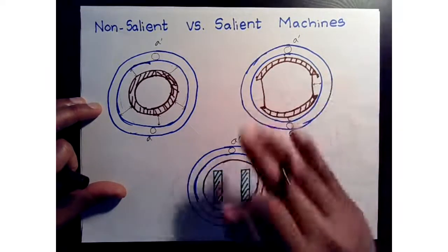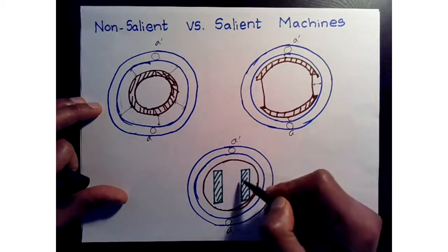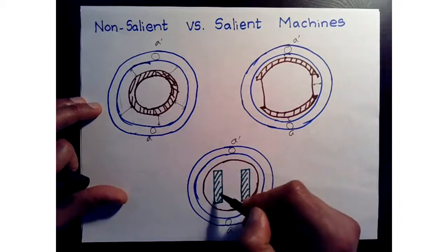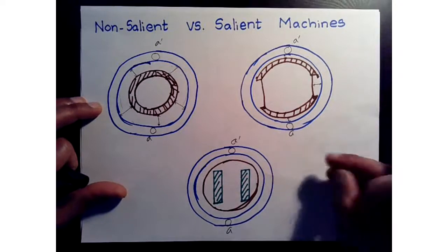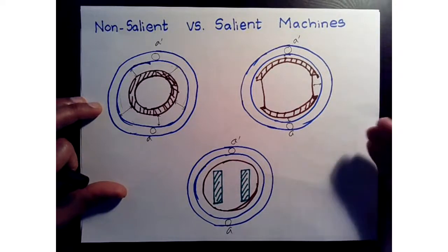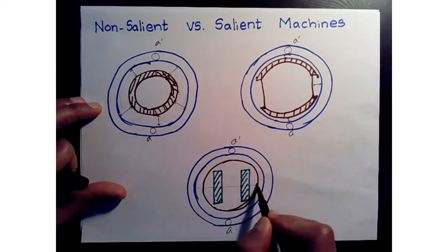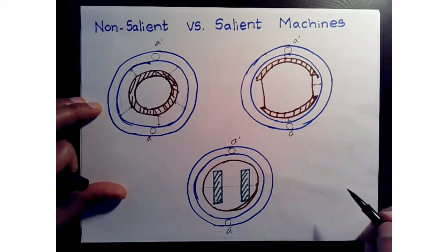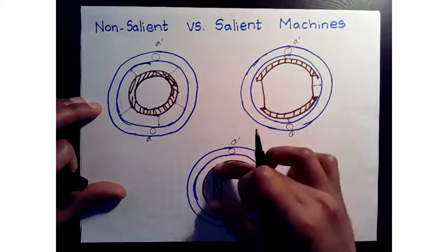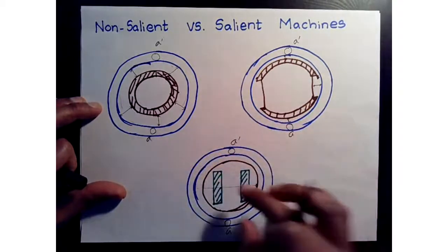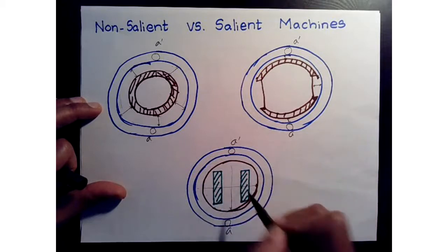Saliency. And same goes for these type of motors. These are called interior permanent magnet motors. The magnets are embedded inside the rotor in specially made slots so that they don't move, or maybe as a design consideration for reluctance torque. So in this orientation we have one set of inductances, and then when you move these to be parallel to this axis, you're going to see a different inductance because you don't come across the magnets anymore.